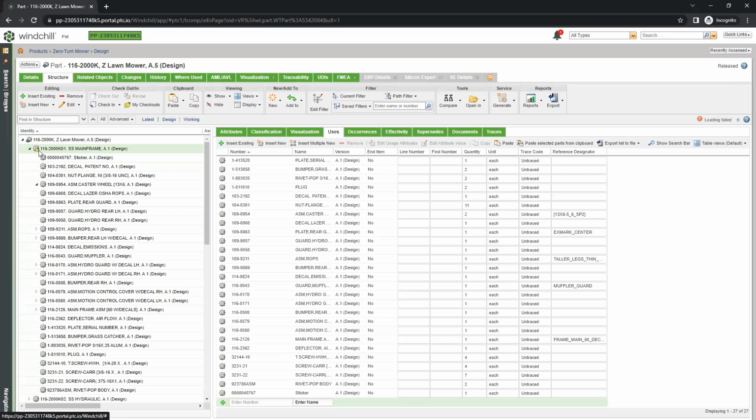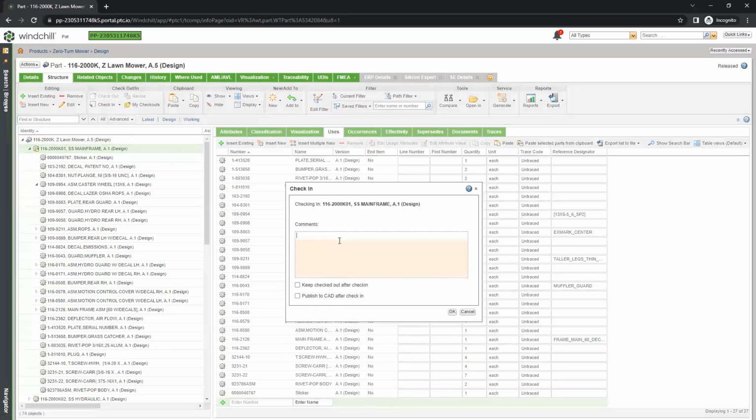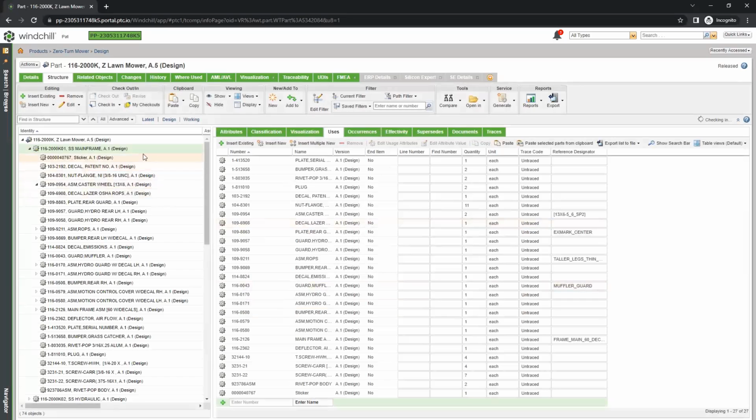People all over the place that don't have Windchill or a similar system are saying that for every assembly or every product or product configuration, we're making duplicates. In Windchill, if they send you, let's say in this case we're looking at a lawnmower, a model of their wheels, because you're not manufacturing the wheels, you're buying the wheels and just assembling them onto your lawnmower, reuse those wheels. I don't want to give myself more work than I need to. So they give you the object. I have a WT part now with that CAD file they provided in it, and I'm just going to reuse it across multiple assemblies.